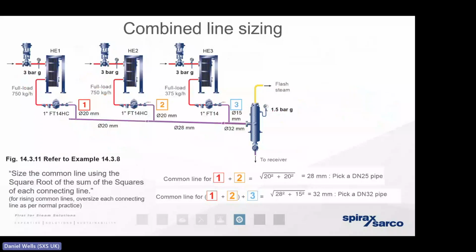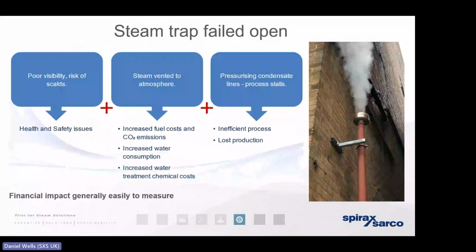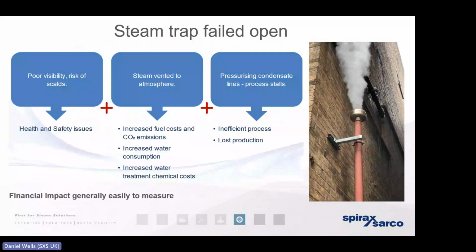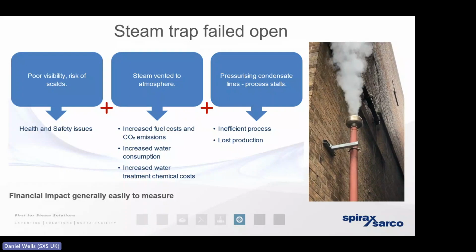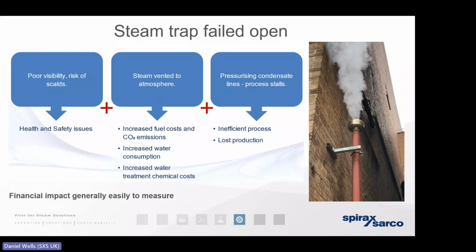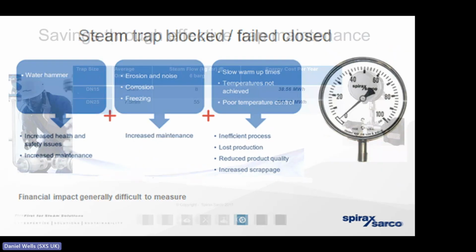So we appreciate that steam traps, they can and they will fail, especially if they haven't been sized, selected, installed, or maintained correctly. And when they fail, especially when they fail in the open position, that is going to manifest itself up those flash steam vents, as we've mentioned, because we need to protect the infrastructure from that expansion. The good news here is we can typically demonstrate the extent of that failure in financial terms if our client has benchmarked their cost of steam.